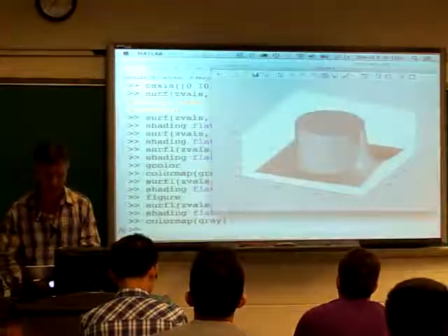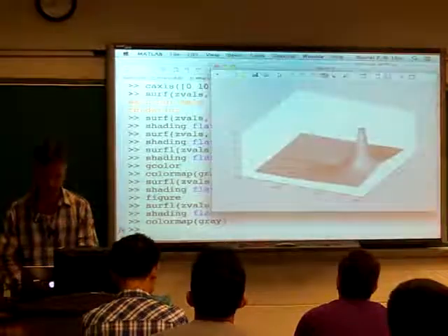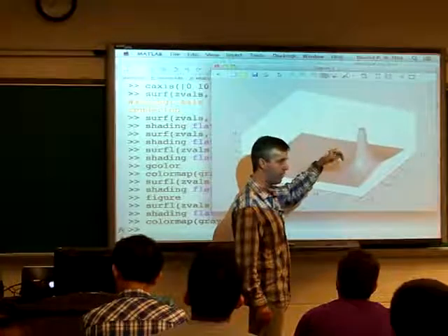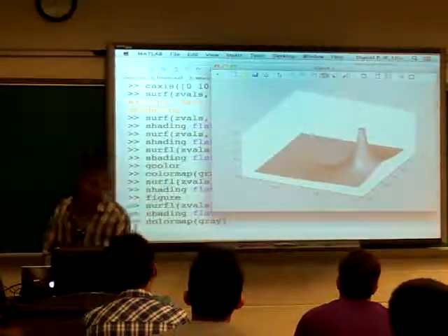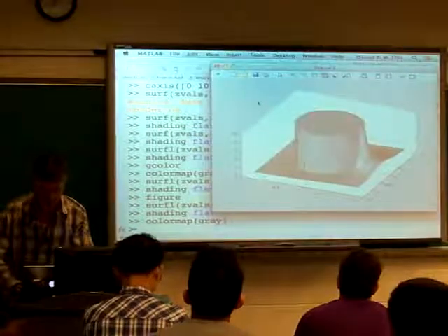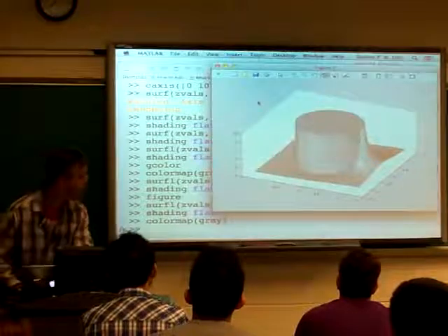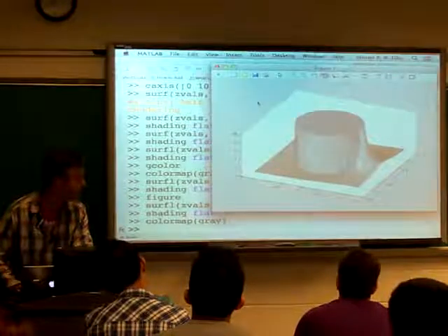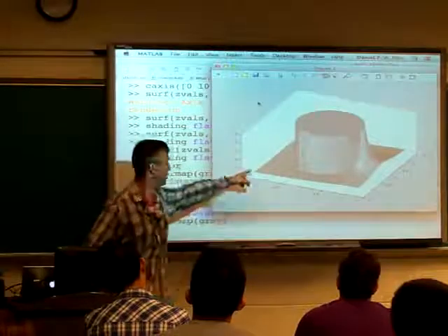That was the other part of the MATLAB demo, and it's actually this. This is just the magnitude of 1 over 1 minus lambda z to the minus 1 for all values of z. And so if you compare these two, I'm just going to alternate between them. You see, this is the actual z transform, but it's the same as the closed form expression within the region of convergence out here.